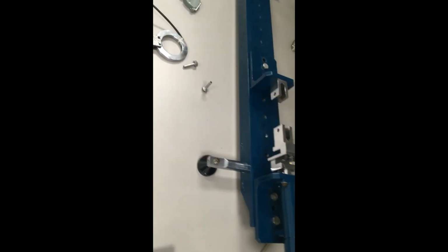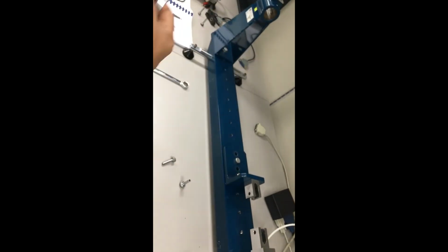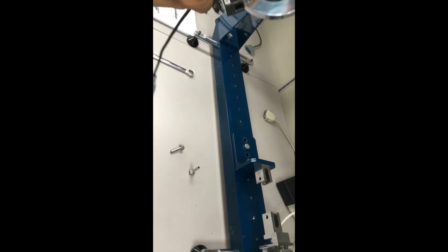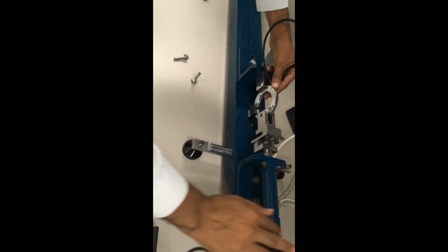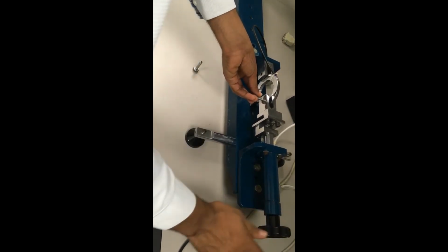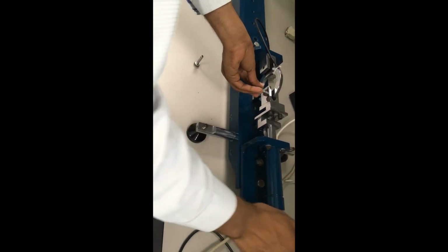Step number 3, we use specimen number 2, which is the curved bar. You see, we will apply some force to test the stresses and strain on this curved bar. So we will fix it in this place here, but we need to turn the knob on right or left in order to have a proper distance, so we can go further. As you see, I need some space to have the pin fixed at this place.